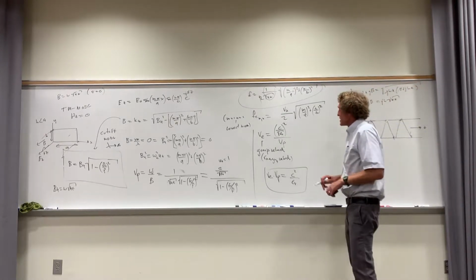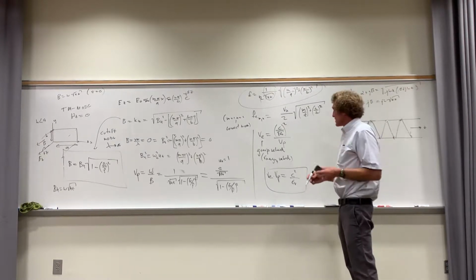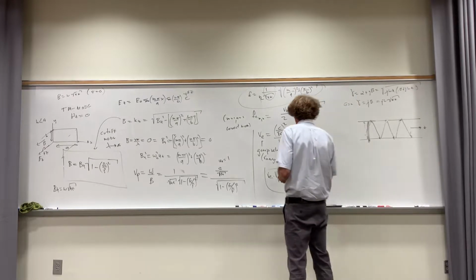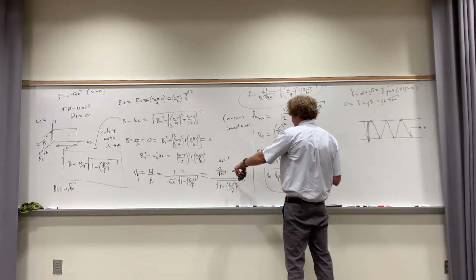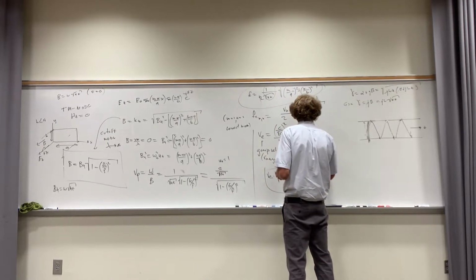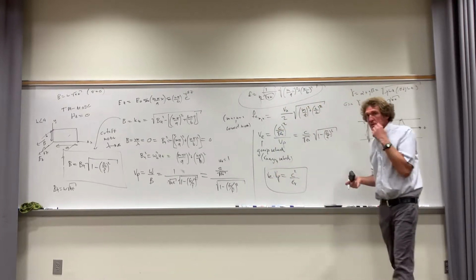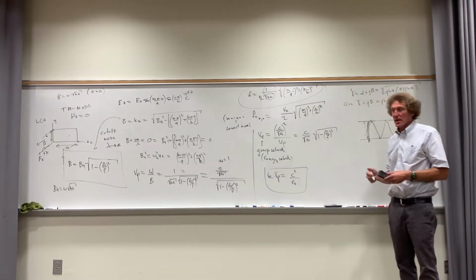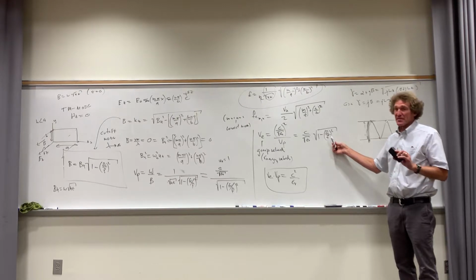So what that means is because the phase velocity is greater than the speed of light, the velocity of energy is less than the speed of light. By how much? If you look here, what do you see? It's actually equal to c over the square root of epsilon relative, times the square root of 1 minus fc over f squared. Do you all see that? So that's how fast energy propagates. And again, the closer you get to fc, the closer you get to the speed being nothing. Do you all see that?